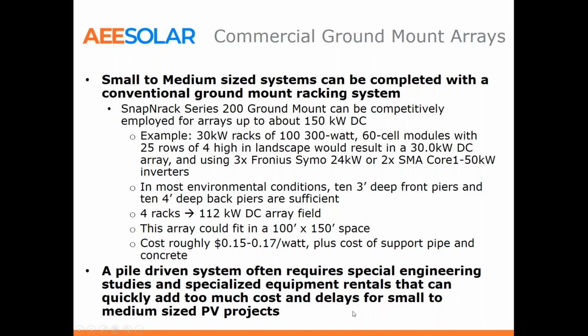So typically, we do see people asking about pile-driven systems, but usually you have to do specialized studies and soil samples to make sure that the piers will stay in place. And then a lot of times for projects with short lead times, the Series 200 system might be much quicker to get permitted and deployed.